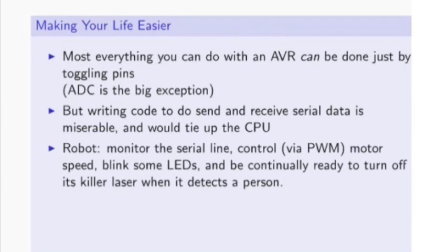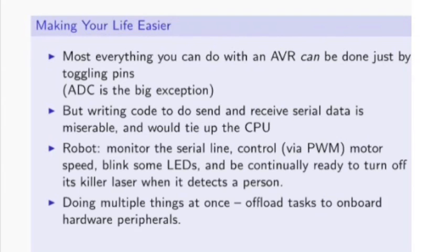If you had to write the code to do all this, even if you could test all those input and output lines, et cetera, it would bog the CPU horribly down. On the other hand, if you can offload all of these tasks to the onboard hardware on the chip, then your CPU is sitting there idle and just coordinating among them. And this is the right strategy to approach microcontroller projects, in my opinion.